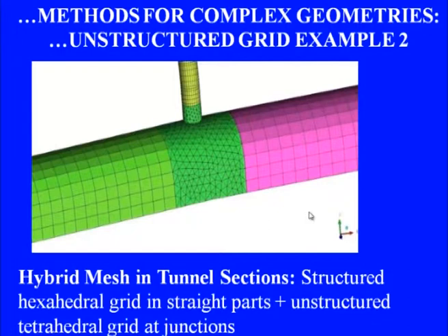So, these two examples of fairly complex geometries give us a fair idea of how we should proceed with the grid generation process: break our overall problem domain into as many subdomains as required. In fluid machinery, there would be even more complications. So, we have to break into maybe hundreds of subdomains and then generate an appropriate mesh in each subdomain and merge them together for final analysis.